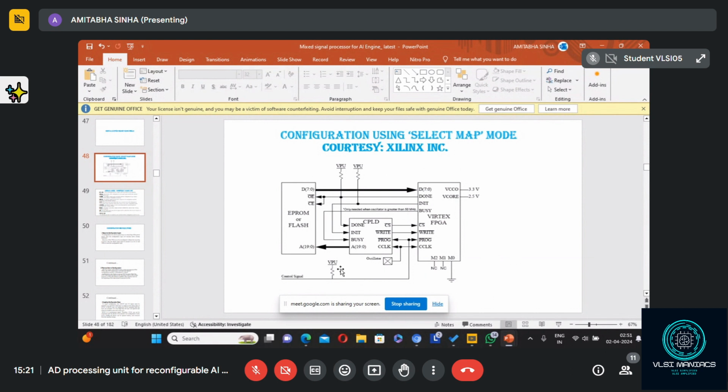Now the question: if you understand this concept, then what is the task of the CPLD? The task of the CPLD is to generate some control signals to the serial PROM and also to the FPGA after getting the command that you download. One thing, this interfacing circuit has not been shown. There will be a parallel port or USB port through which a CPU will be connected to the CPLD.